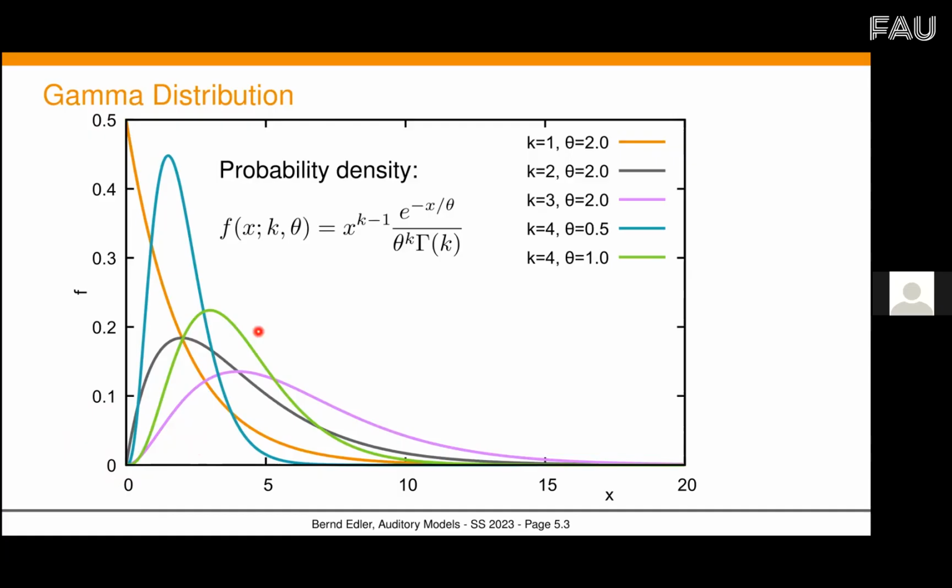The higher the order, the more you multiply by a polynomial of x, so the flatter the curve gets out of 0 and then bends up. That's how the order influences the total shape. In practice, for gamma tone filters, an order of 4 is often used, so the curves would have shapes like that one or the green one and so on.